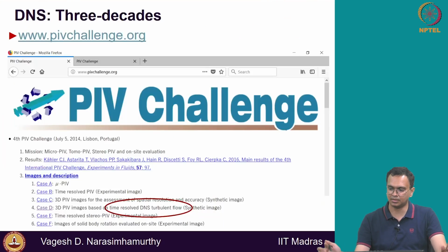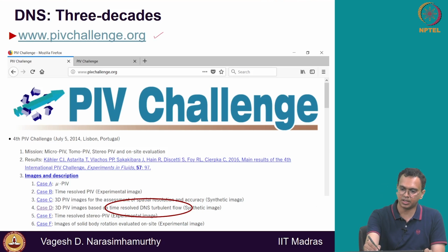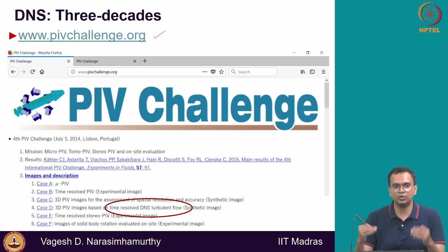And finally, this slide. PIV is an experimental technique, a state-of-the-art experimental technique today for measuring turbulent flows. Usually we use experimental data to validate CFD. But today you can see this website called pivchallenge.org, where the manufacturers of these PIV systems have to validate that their experimental setup is correct before people start to buy it.